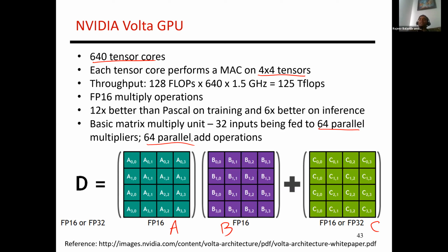And it basically takes, there are 16 inputs here, there are 16 inputs here. So it takes those 32 inputs and does a broadcast to all of these parallel multipliers. And so in that sense, it's a little different from the Google TPU, which uses the systolic data flow. This one is, I believe, more broadcast based. And so it operates at a smaller scale. We are only operating on 32 inputs at a time, doing all of these operations in parallel, producing that result.